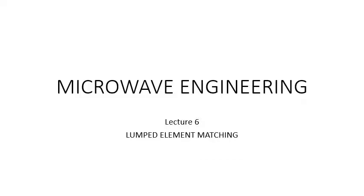In today's lecture, we are going to learn about lumped element matching. First of all, what do you mean by a matching network? Matching network means that type of network in which we get the value of ZL, that is load impedance, equal to characteristic impedance, total matched impedance. Total matched impedance means zero reflections and VSWR value becomes equal to 1.